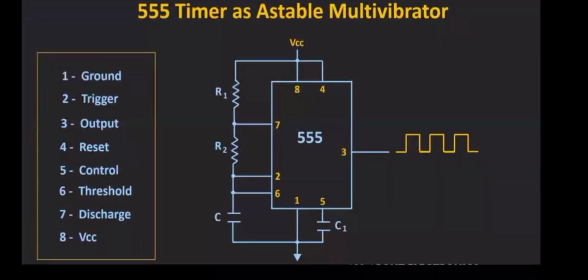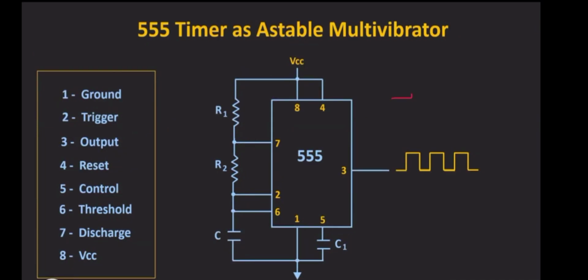So listen carefully here. An astable multivibrator. The 555 timer is used as an astable multivibrator, the chip which is used to generate a clock pulse, wherever you are using a clock button or a push button. So the 555 timer used as an astable or free running oscillator, free running meaning it will be generating continuous waveforms.